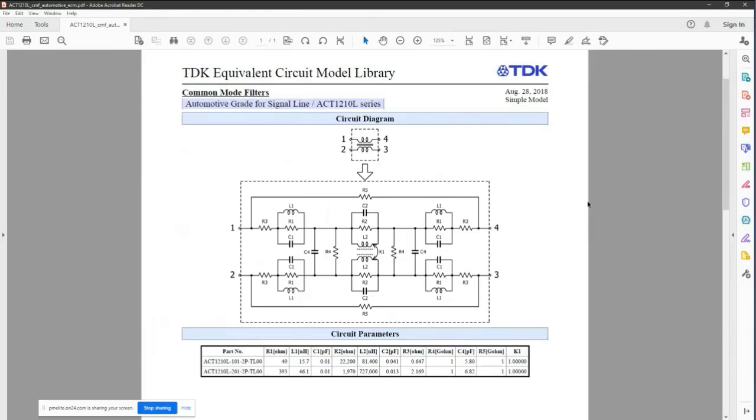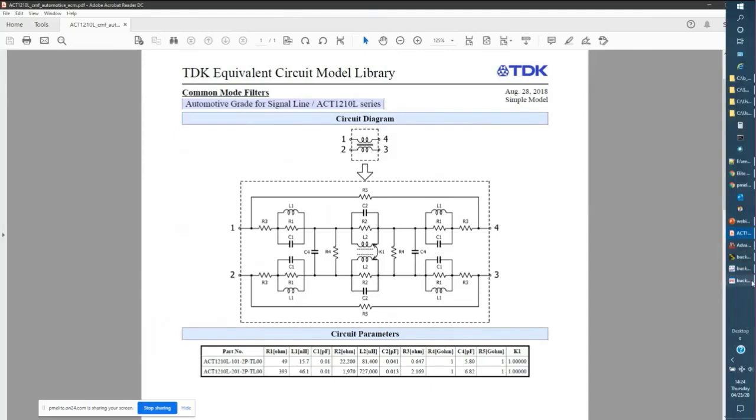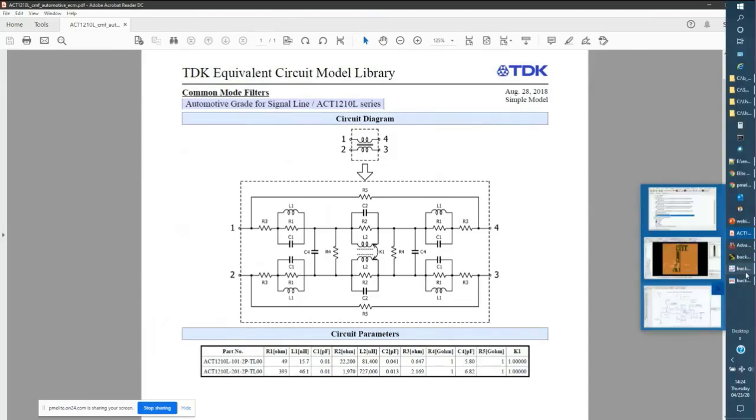If you ignore this and you just try and model this as an ideal component, then all of the effort that you put into the analysis and the results post-processing is not going to be very helpful, because you will have perhaps walked past a fundamentally important issue that you're never going to see, because your model doesn't incorporate the parasitics. So let's go back to the layout.